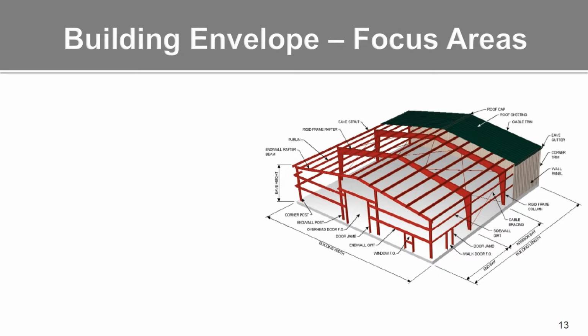First off, let's have a brief overview on what would be considered a metal building in the energy codes. If you just simply have metal cladding, like metal wall panels and metal roof, and if you have metal studs, vertical studs, that would not be considered a metal building. A metal building in the energy codes assumes for the walls you have horizontal girts, whether they're C shaped or Z shaped, and they're spaced about 5 feet on center.